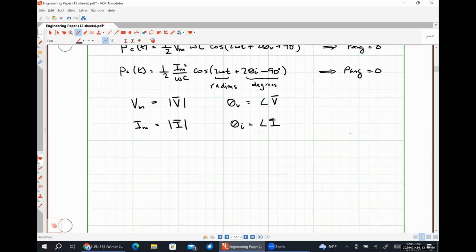All right. So before we move on to our next topic, any questions about instantaneous power in a single phase circuit like we've got here? Caden, yes, sir. So that means the capacitors and inductors absorb no power. No average power. Yes, they do not absorb average power.